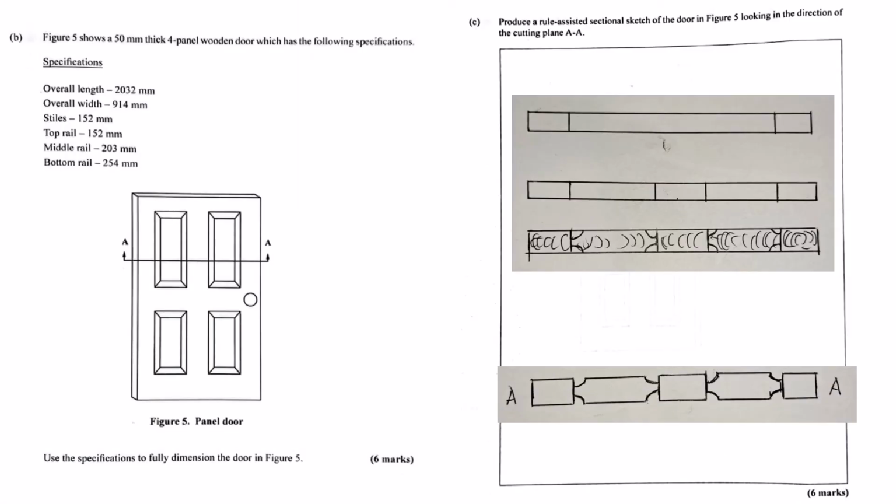Okay, let's shift to something more tangible. A panel door. We had some measurements for one. How do we use the overall size to figure out the size of those inner panels? Right. This is a perfect example of how the big picture breaks down into smaller parts. You start with the total height and width of the door, the overall dimensions. Then you've got the stiles, those are the vertical pieces running at the sides, and the rails, the horizontal pieces, top, middle, and bottom. Think of them like the frame around a picture. Right, the structure holding it together.